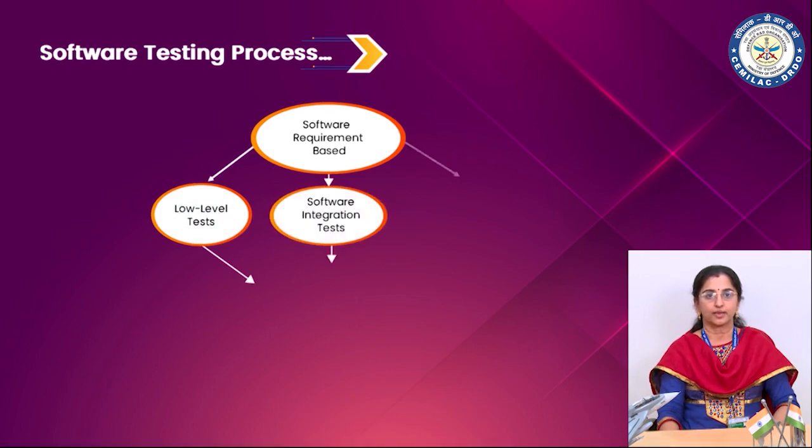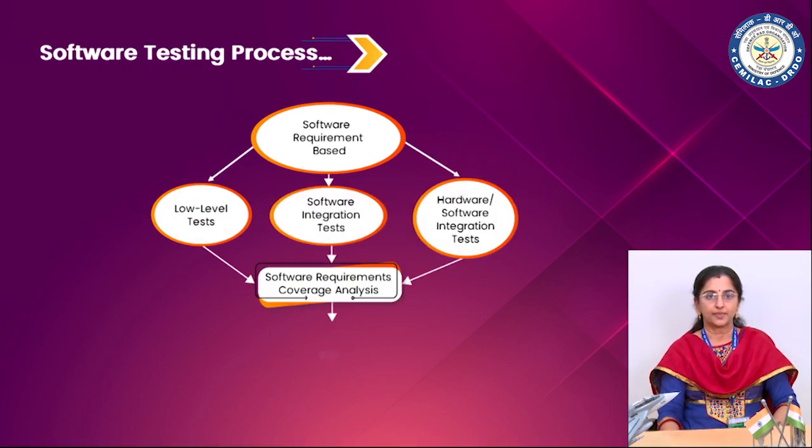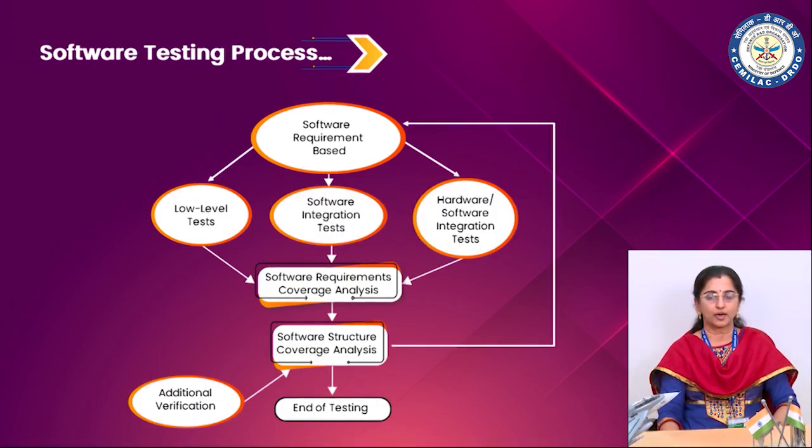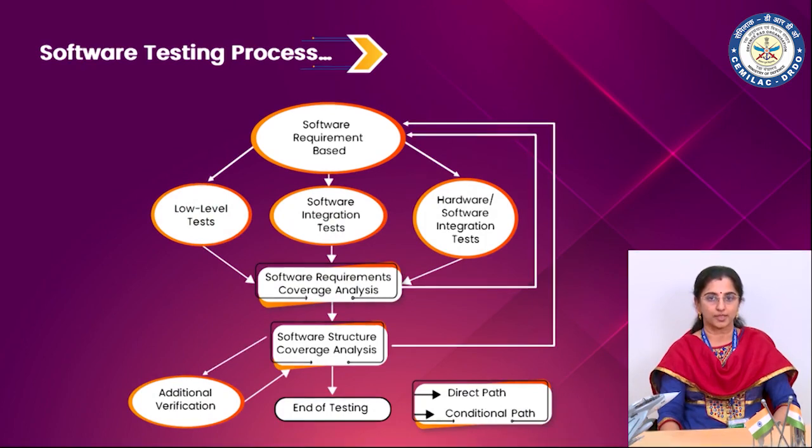Now this figure in DO-178C depicts the software requirement-based testing process. The software requirement-based low-level test, the software integration test, and hardware-software integration tests are carried out together with the aim of achieving complete software requirement coverage and also the software structural coverage.